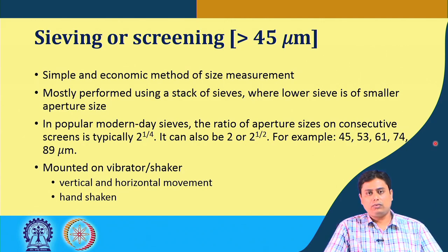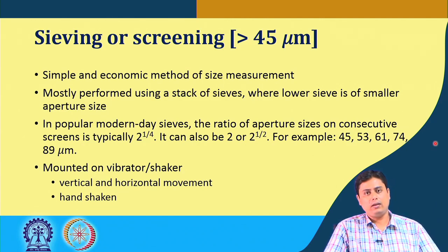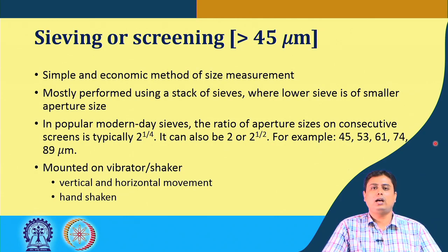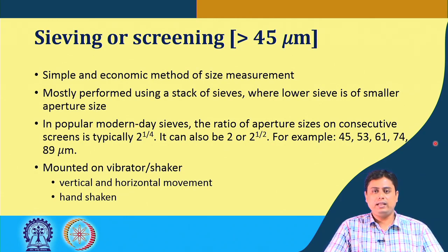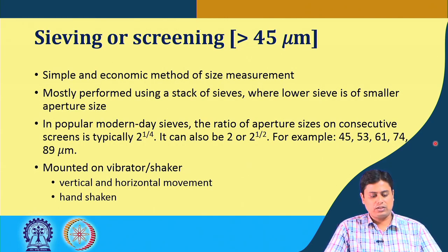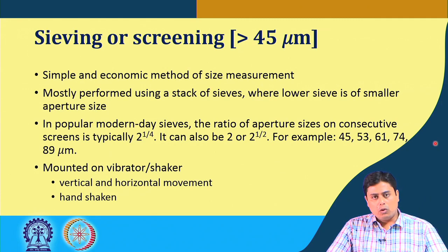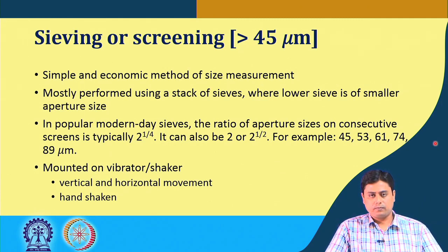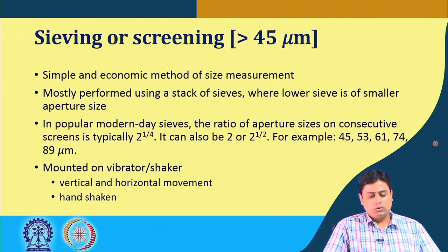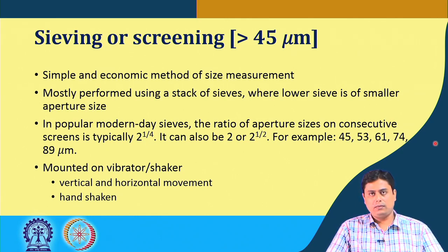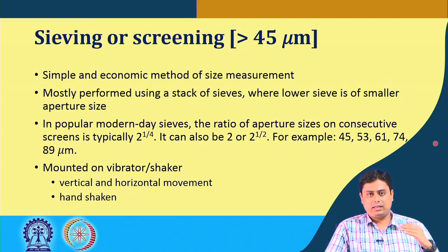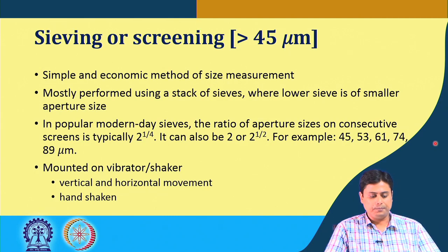So, a similar kind of principle is applied in sieving or the screening technology, where bulk solids are put into the strainer, basically a cascade of strainers or screens, and in most cases it is vibrated in vertical as well as in horizontal directions. So, these are the stack of sieves, where from top to bottom, where it is firstly fed, the aperture sizes are bigger and then smaller, and consecutively it goes smaller and smaller.